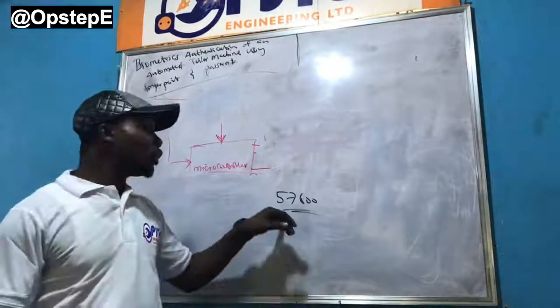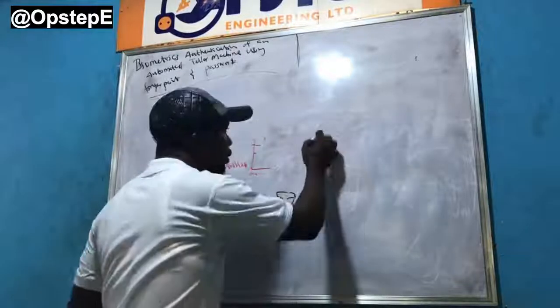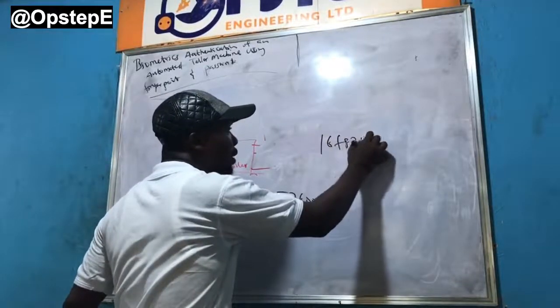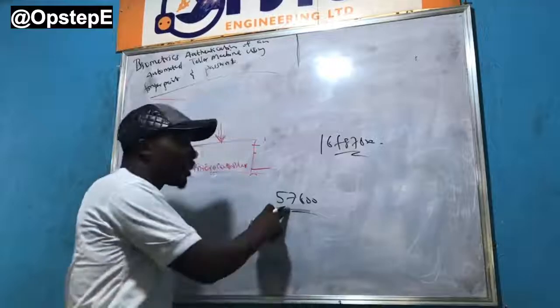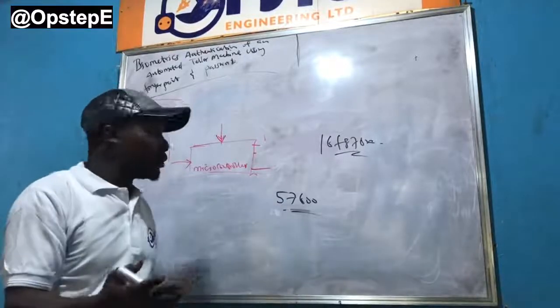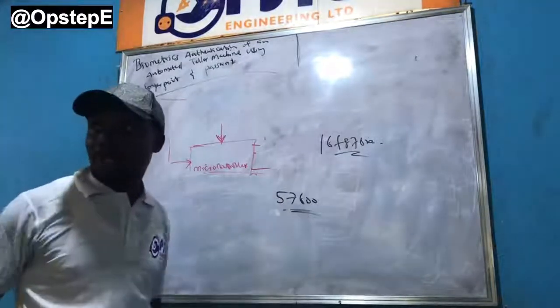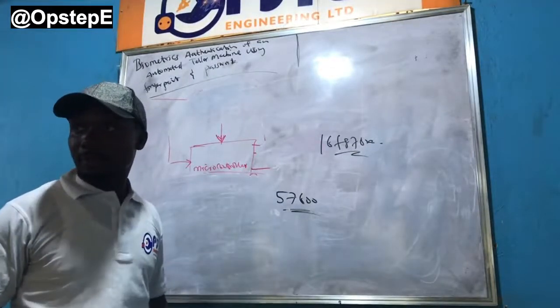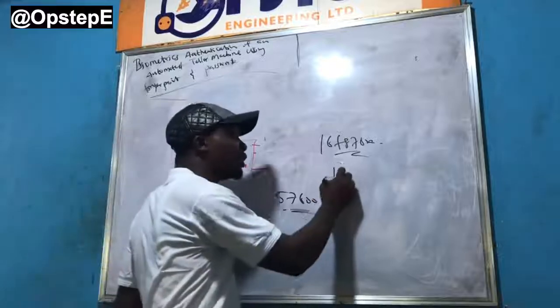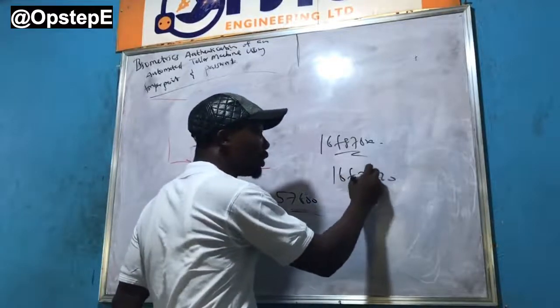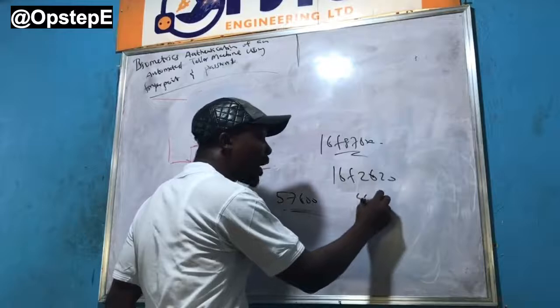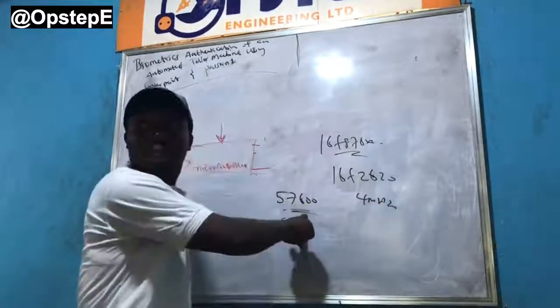Now, if I was using the 16F876A, I might not be able to actually use this baud rate with a 4 megahertz crystal. I might not even be able to use it with a 20 megahertz crystal. I'm not sure, but we can test it. But when I begin to use the 18F2620, even at 4 megahertz, it allows this baud rate.